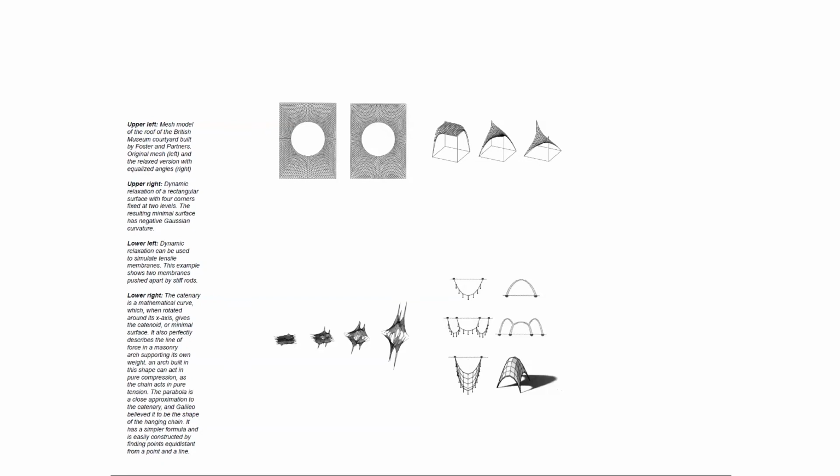So in order to build more efficient masonry vaults, you need to work with these sort of paraboloids. And that's why, again, the Gothic arch is a pointed arch. So it's not exactly a paraboloid, but it's something very close to it. Okay, so a pointed arch is as close as you could basically get there, I guess. There are some other reasons why it's pointy, I guess,